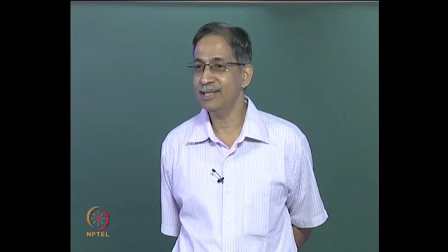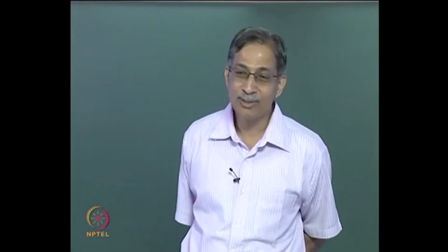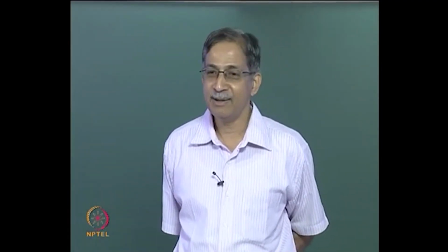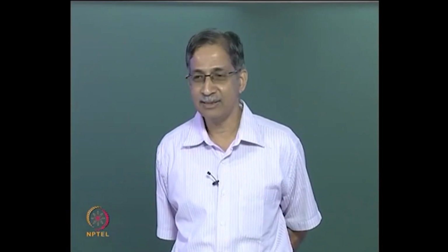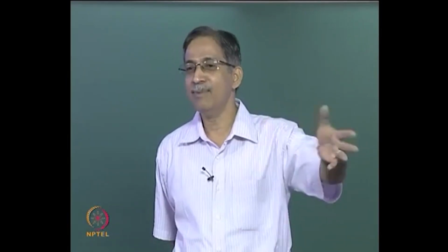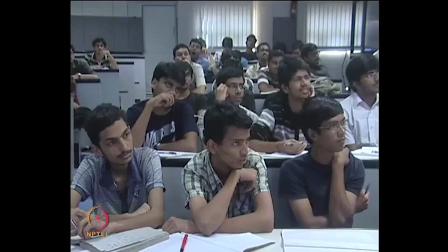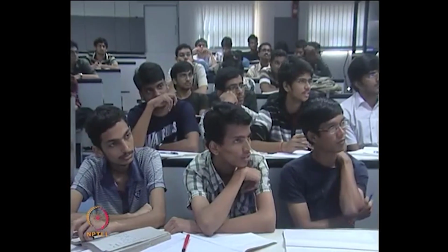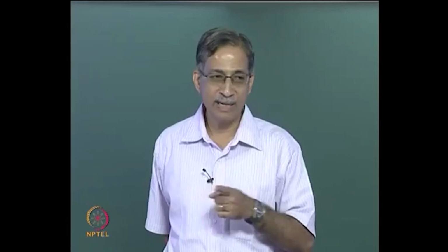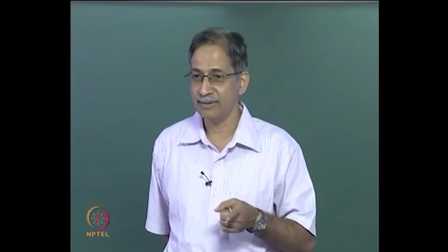Really beautiful. Just 0.9 kilonewton is the force that you get, not 20 kilonewton, not 40 kilonewton, not 100 kilonewton, not 990 kilonewton. So at the end of the day, you will find that thanks to this analysis, you can confidently say, I don't need to worry about temperature changes for a frame like this. But you wouldn't be able to say it with that degree of confidence unless you could analyze the structure and interpret the results. Is it clear?